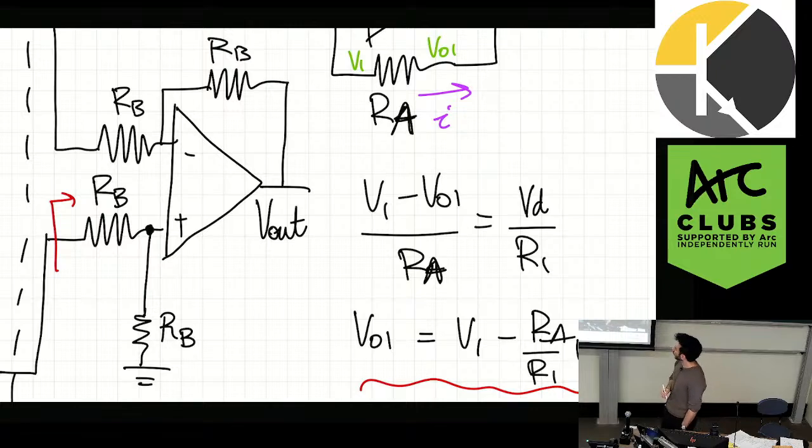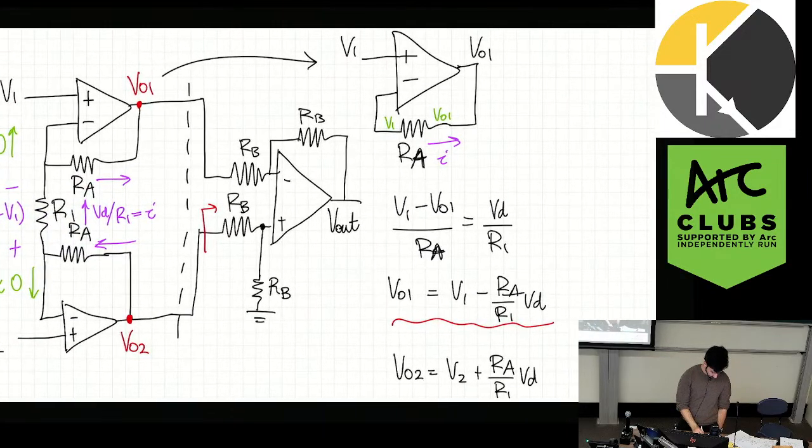But it's highly dependent on the resistor values in that case. Again, if we're just using this circuit alone, no pre-buffer stages, the common mode signal and the rejection ratio is highly dependent on those resistor values, which vary quite a lot in fabrication. What's the difference when I have an instrumentation amplifier? Why isn't this as much of a problem?